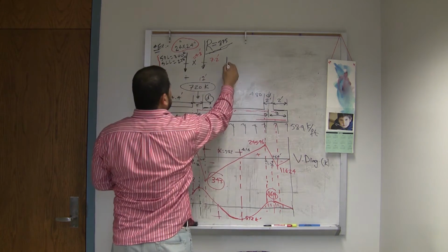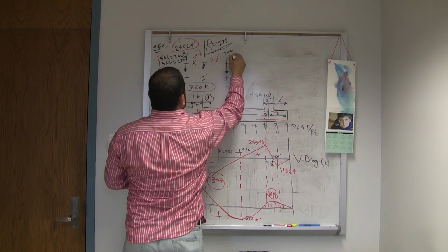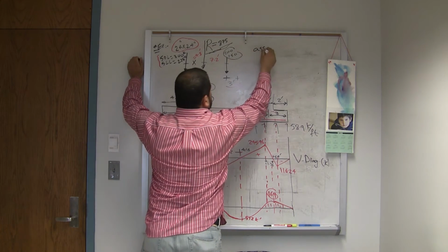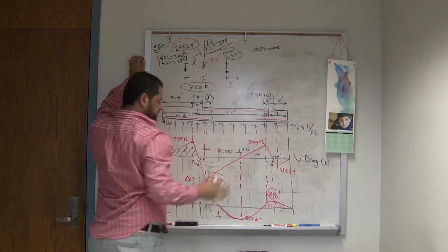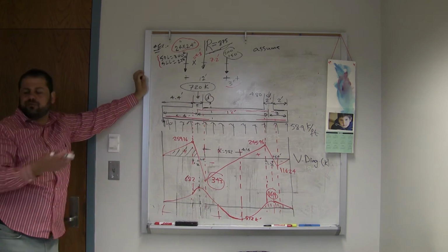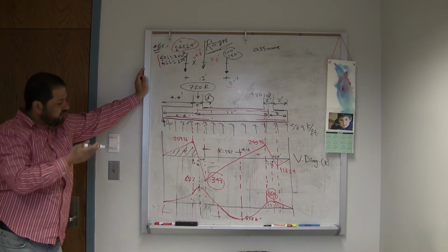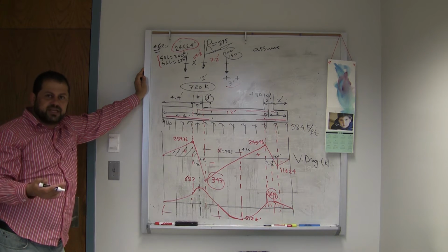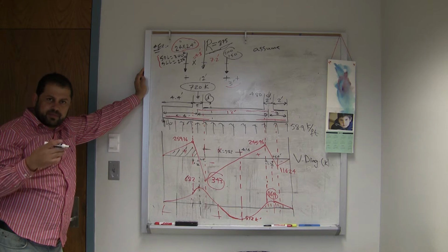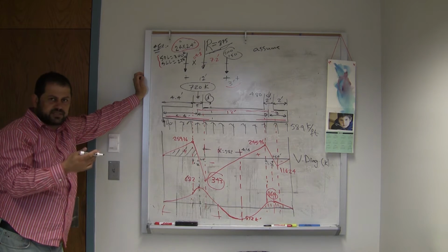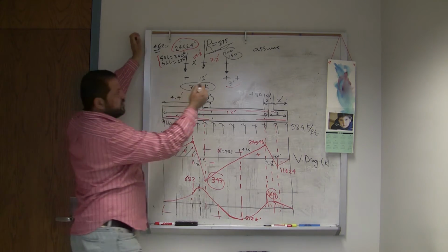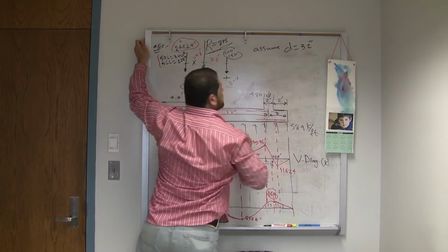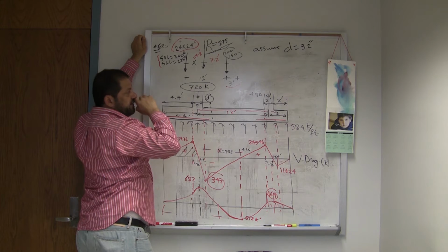This is 200 and 150. So assume this is a major footing. I may assume D equal 2 foot, or if I assume the overall depth of the footing will be 3 feet, which is 36 inch, and we know we usually subtract 4 inch to the center of the steel. So let's go with D equal 32 inch.